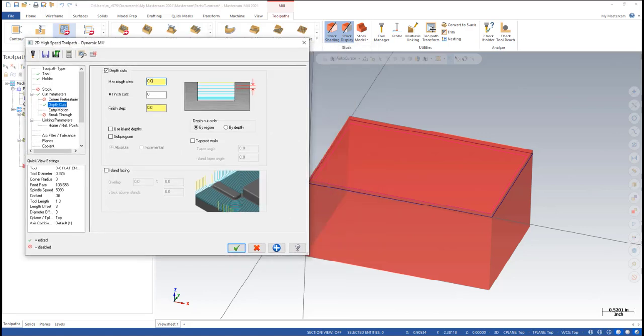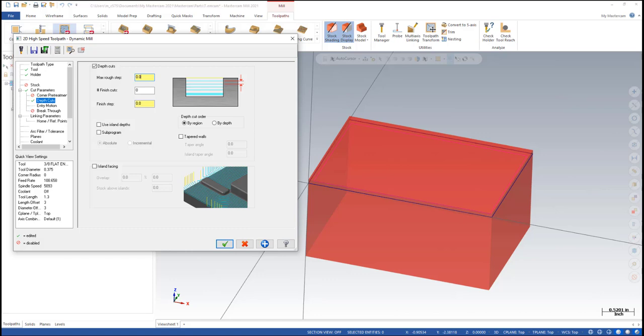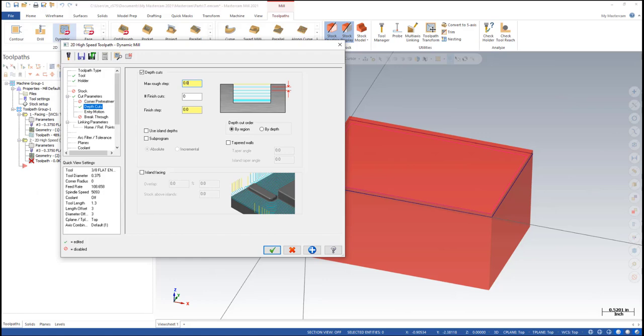And the only downside to doing depth cuts is you get these sort of blend lines at every point where the tool moves down to a new lower low. You get horizontal lines on your part. But because we're going to clean it up with a contour, it doesn't really matter. So we'll just do this to keep the load on the tool and the machine under something that's more manageable than trying to engage it all at once.